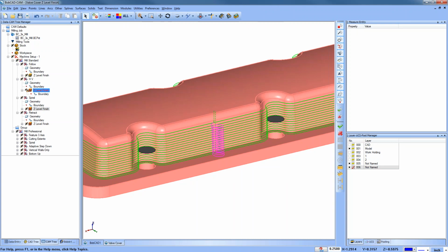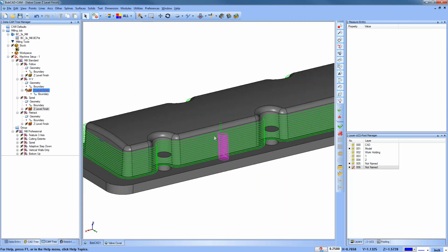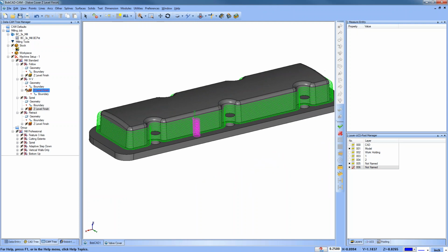No. The 3D toolpaths do not use cutter comp. There's no cutter comp setting for any of the 3D toolpaths, so it's not going to post the G41, G42. It is possible, using advanced posting blocks or editing the code, to put cutter comp in there, either through a special post processor or through manually editing the code. But then what you're asking is, I want to lead in and lead out and use cutter comp on every level.